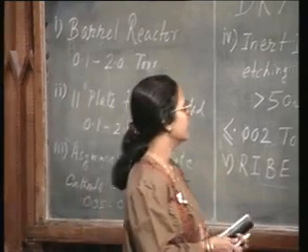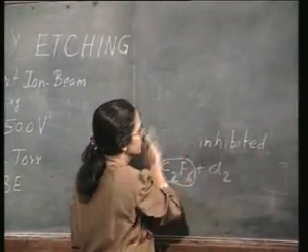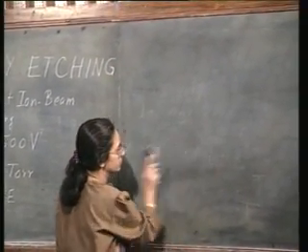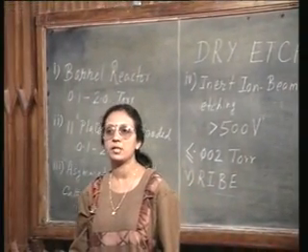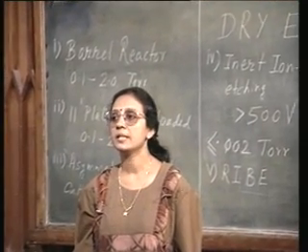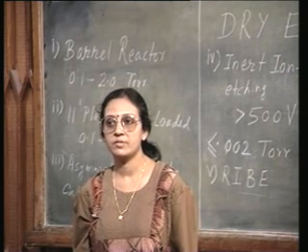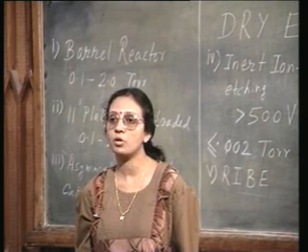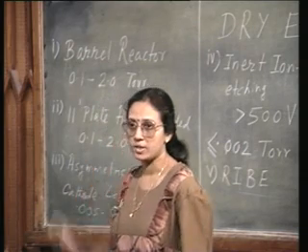And then finally, we have what is called microwave plasma. All these cases, all these reactors, I said that they generally operate at RF 13.56 megahertz. That was the most common RF frequency employed in all these plasma reactors.